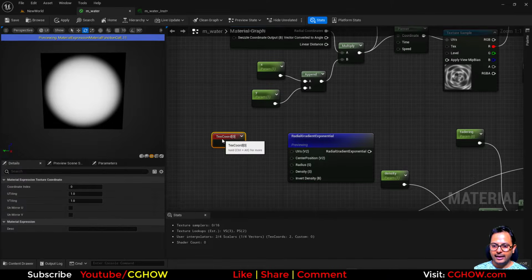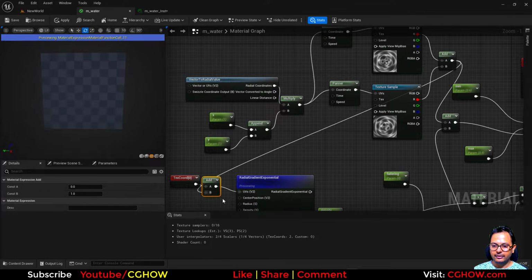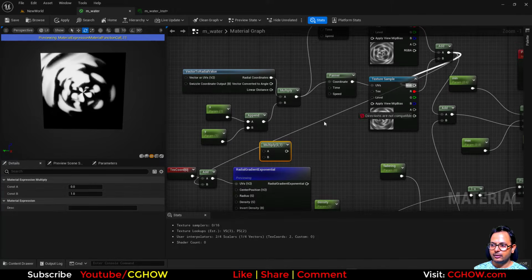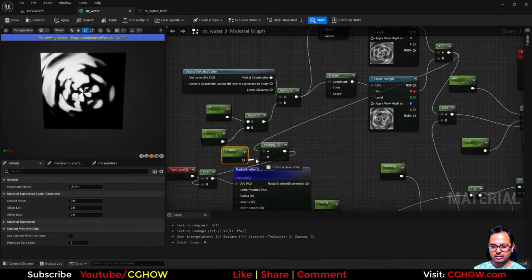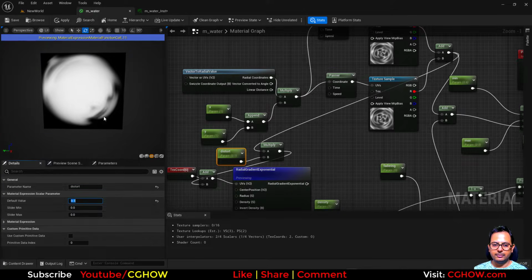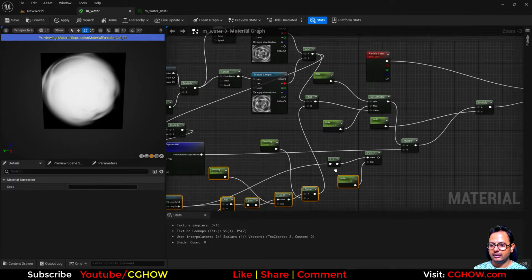And if you add something in the UVs like this noise texture, it will distort that completely. But you can use a multiplier to control that, and you can make a parameter distort. So 0 means nothing and 0.1 means there is some distortion. And then you can use this here instead of this. So you don't need this whole thing, you can just remove that.